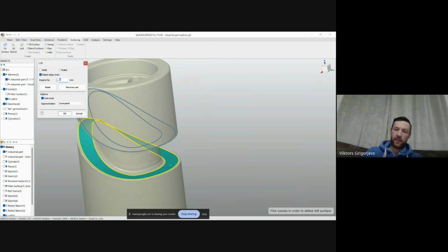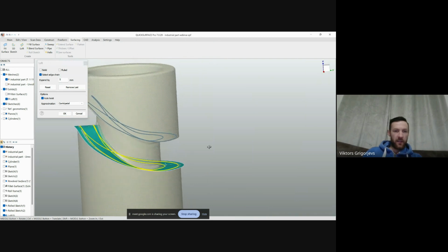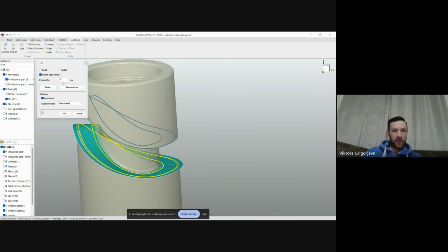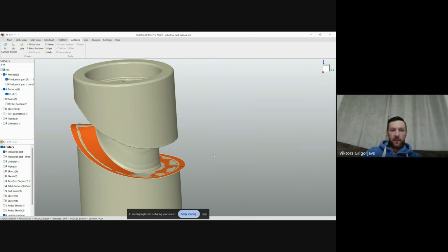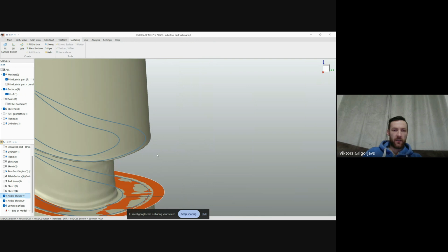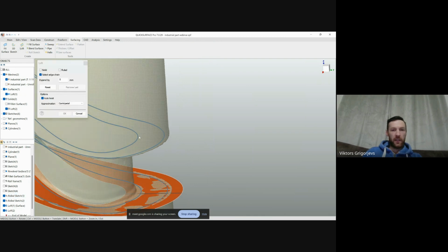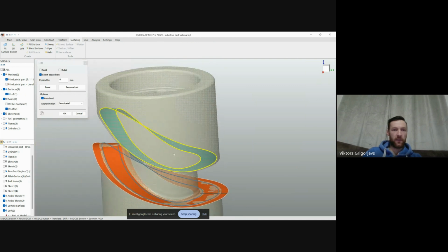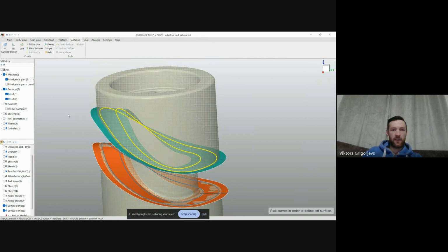So you're just setting extend, for example, 5 millimeters, and we can do more just in case. Okay, coming back, switching back our sketches, repeating the loft function on our top surface of this groove, extend by 7. Okay.